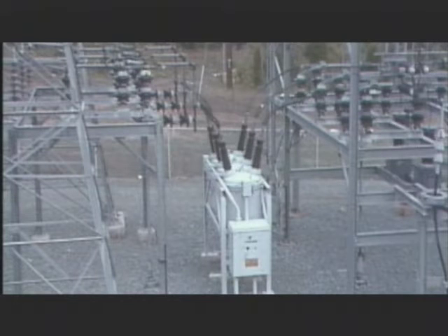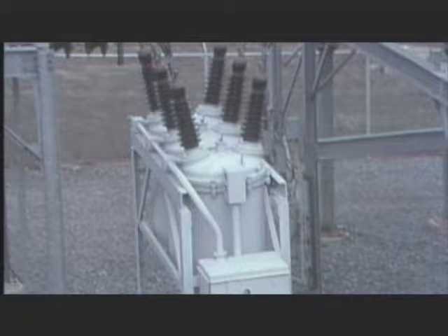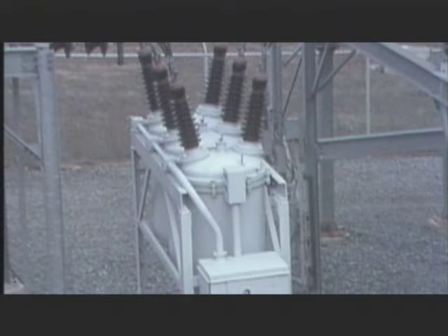In both form and function, a substation is a lot like a switchyard. It just handles power on a smaller scale. The disconnects here serve the same purpose as switchyard disconnects. They are used to isolate equipment and lines for maintenance and repair. Circuit breakers are used to switch the power on or off in the substation. By opening and closing circuits, they also direct the flow of electricity to the appropriate lines for distribution.